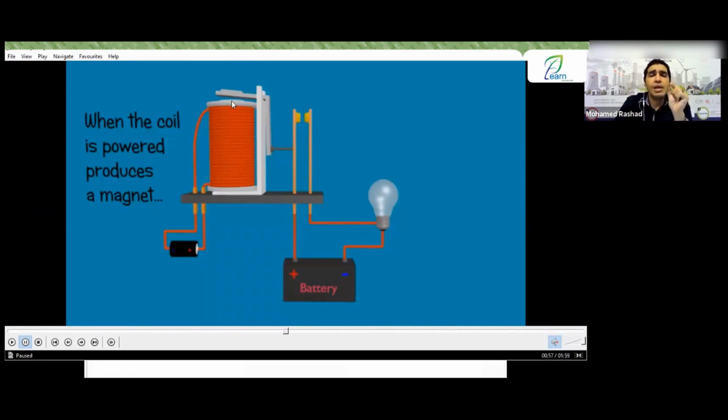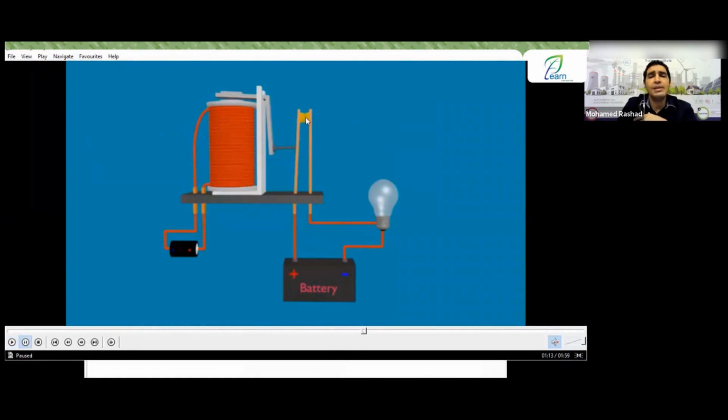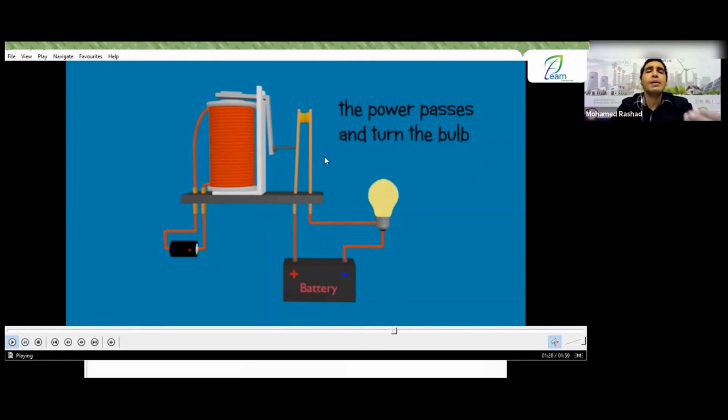It then begins to pull the armature inside here with the magnetic field, which you can see. When it pulls this armature down completely, look, what will this arm do? It will push the contact. Look, it goes down gradually and pushes here step by step. As soon as these two touch each other, meaning they become closed, the circuit is closed with a lamp in the circuit with an indication alarm, as we will see. Once they close, you can use this contact in any circuit as you wish.